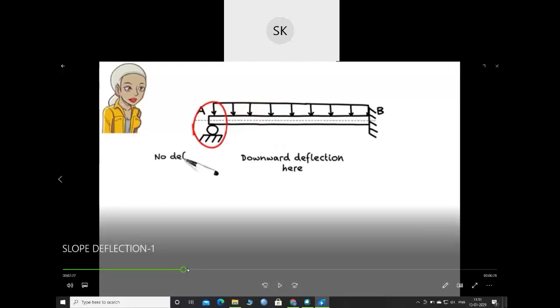Here are a few examples illustrating this process. Example 1. A beam is subjected to a uniformly distributed load of 2 kilonewtons per meter. What are the support reactions? The beam is 10 meters long. First, let's replace the distributed load with a concentrated load.